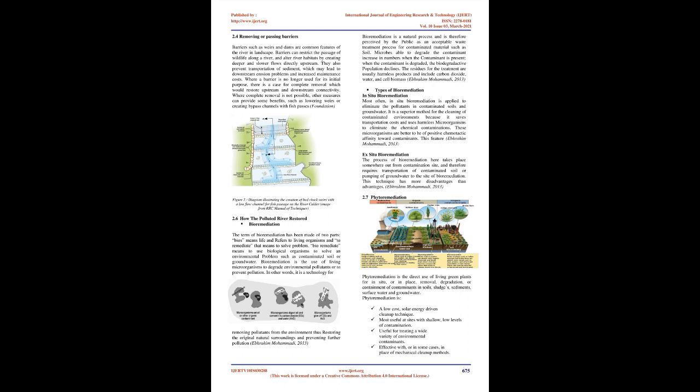Floodplain reconnection and wetland creation. Floodplains are an important aspect of a riverine environment, providing flood storage, fish refuge, and habitat diversity, but often they have been disconnected and drained to protect housing from flooding and create land for agriculture or development. This disconnection and reduction in storage may cause a greater flood risk downstream as water moves through a catchment quicker.